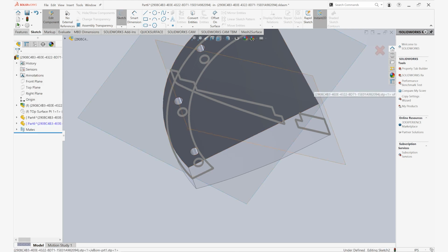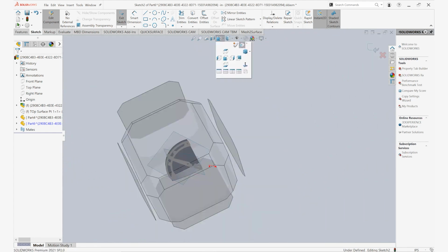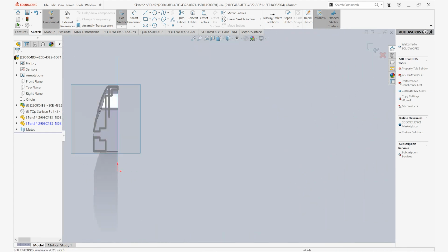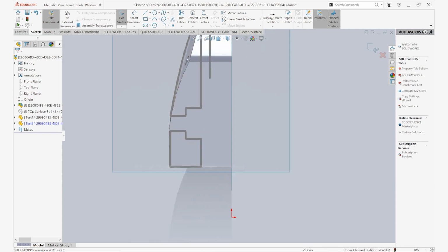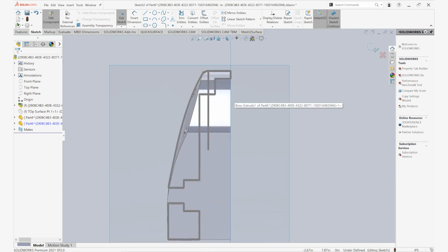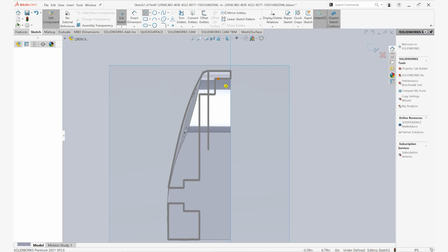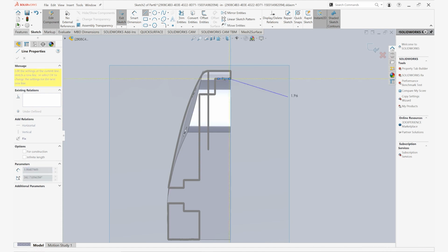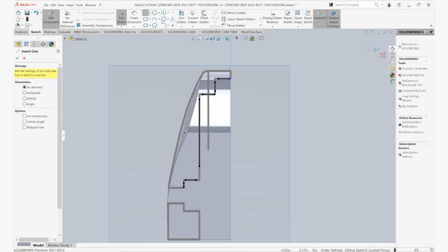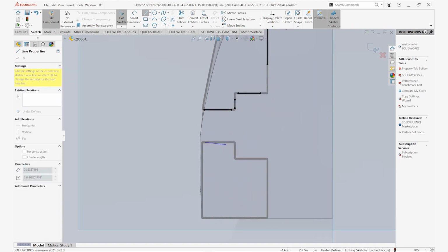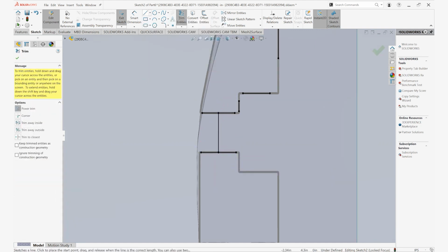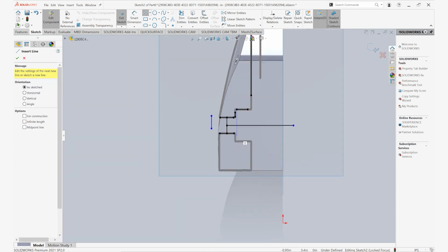Now that we have the basic solid object, we have some internal geometry that we need to cut away. So to cut away this internal geometry, it's mainly revolved around one central axis. And for this video, we will be simply creating the 2D sketch around the perimeter of our part and then revolving that away as a cut. There are a variety of different ways that we can achieve this goal. We could import the primitives from Artec Studio and use those to cut away the geometry, or we can just accomplish the same task with one large revolved surface.